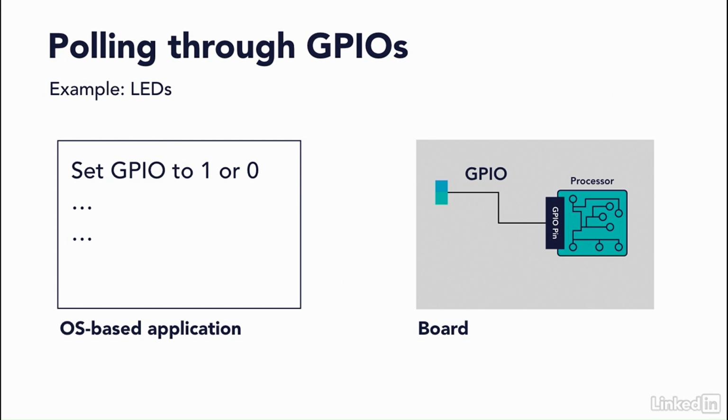Besides its simplicity, polling generally takes CPU time for waiting and polling the device. Alternatively, interrupts are considered a generally efficient way to interact with peripherals in real time. Instead of polling peripheral data from our program, the peripheral device will notify our program with interrupt events. In this case, an operating system usually provides the interrupt service routine to handle interrupt events for our applications.